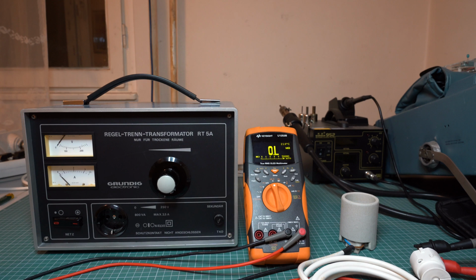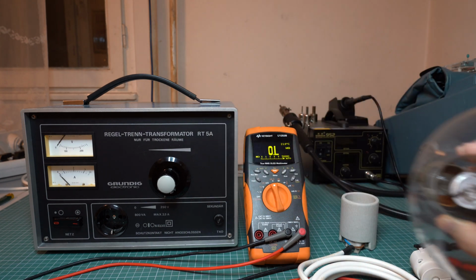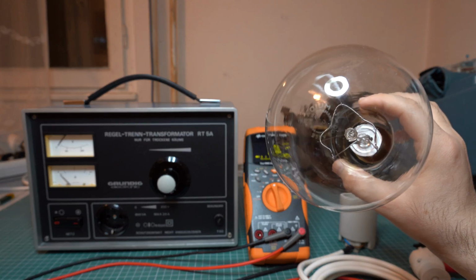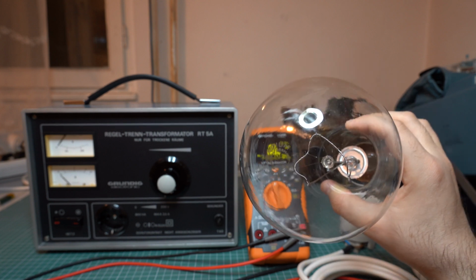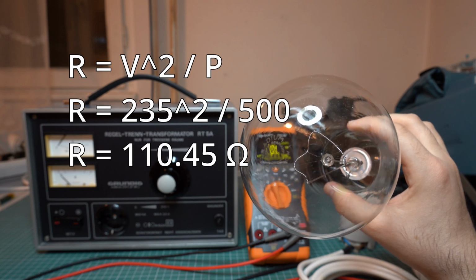Other exceptions from Ohm's law are non-linear circuit elements, and one such element, believe it or not, is the incandescent light bulb. Let me show you what I mean by that. By looking at the parameters of this light bulb, we can see that it's supposed to run at 235 volts and it has a power of 500 watts. So by doing some simple math, the resistance of the light bulb should be around 110 ohms.